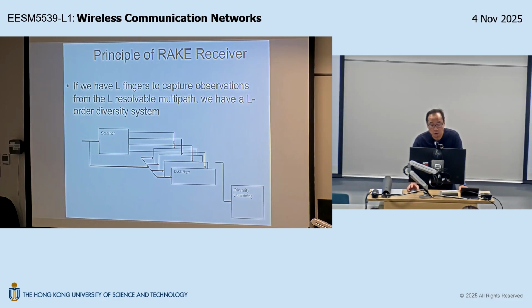So last time we illustrated how spectrum interference suppression can help to eliminate or suppress two types of interference in a cellular network. One is the multi-user interference. Remember, in a base station operated using CDMA, all the users' transmissions share the same time, same frequency, right? So they're not separated by time, not separated by frequency. So how do we separate the signal? By making use of this selective reconstruction of the signal from a particular user. That basically is one instance of interference suppression, in particular suppressing the interference from multiple users.